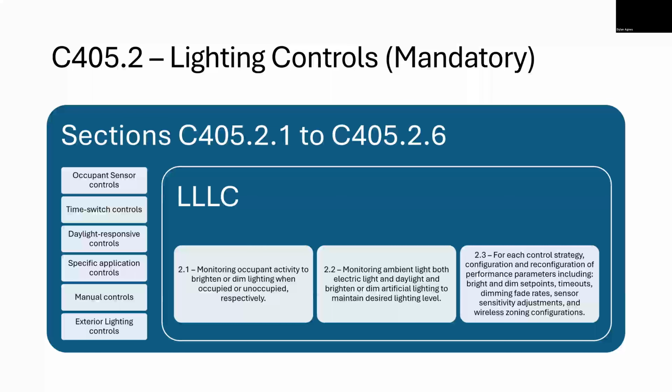So the LLC standard is held by the IES, the Illuminating Engineering Society. They create the threshold for what is considered LLC. And theoretically, this is how they model it: when code is here, LLC compliance is here; code moves up and LLC moves up. So it's supposed to be a straightforward, out-of-the-box solution. The only thing you have to worry about is making sure you're programming the controls correctly, and that's mostly done in the commissioning part. So it's a way to simplify the process.